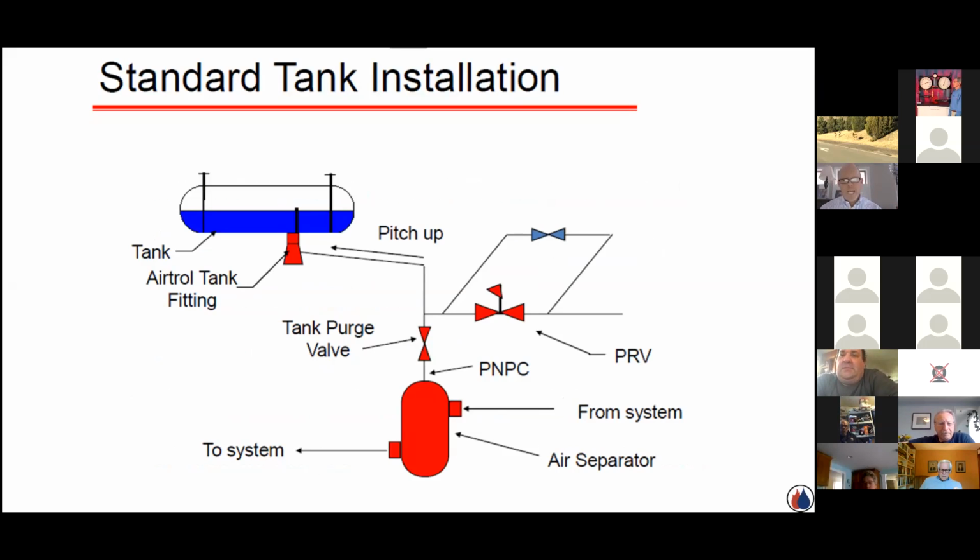So, a picture of an old style coming off of some type of commercial air separator. I don't want to vent the air. I want to direct it up to that tank and replace that air. So I never want to have automatic vents in one of these old style. Whenever you walk into a basement and you see a steel compression tank, if it's still active, make sure there are no automatic vents, because an automatic vent does a very good job of releasing air. I don't want to release the air. I want to catch it and control it.